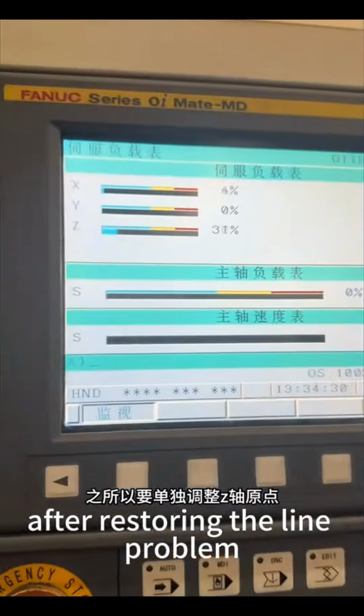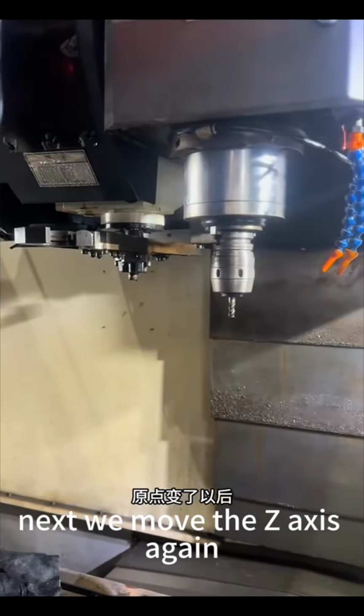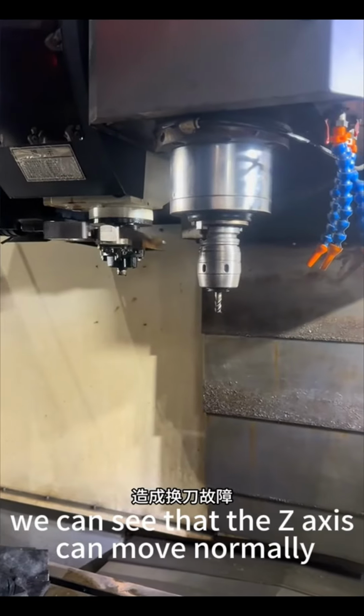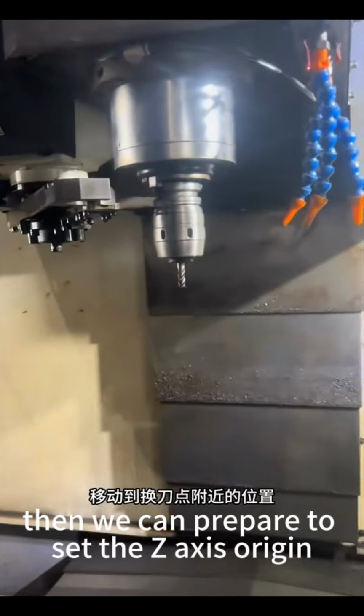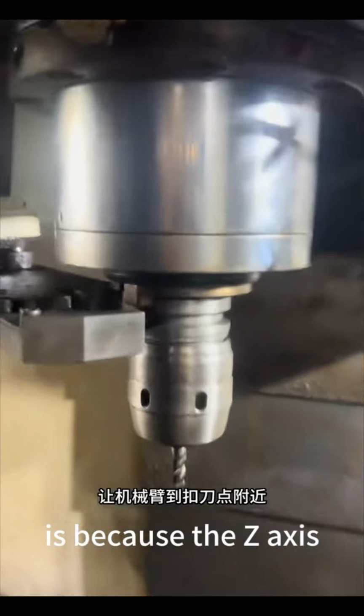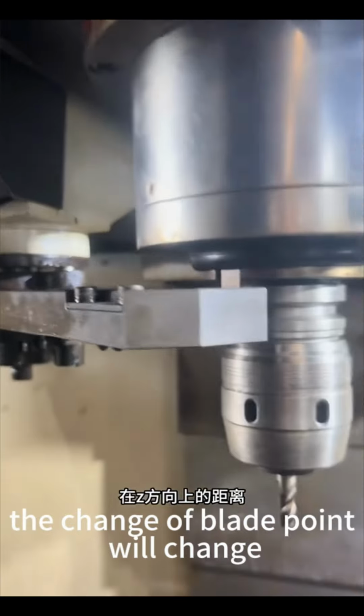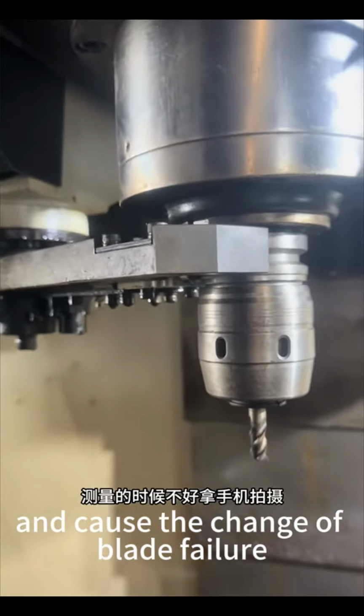After restoring the line problem, we can see that the brake accumulator has returned to normal. Next, we move the Z axis again. This time, we can see that the Z axis can move normally. Then we can prepare to set the Z axis origin. The reason for adjusting the Z-axis origin alone is that the Z-axis is involved in the tool change. After the origin changes, the tool change point will change and cause tool change failure.